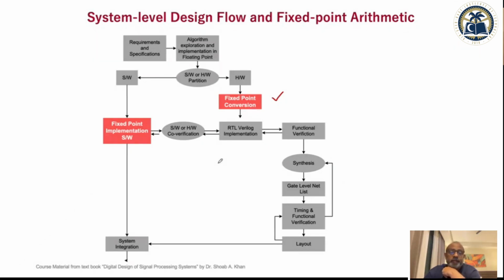Once you're doing hardware design, sometimes you have no other option but to use floating point. But most of the algorithms are all floating point algorithms, and anything that goes into hardware you need to convert into fixed point. Anything that goes onto digital signal processors is also usually converted into fixed point, because though most of these DSPs are floating point processors as well, there's a difference in cost and power dissipation, so you convert them into fixed point.